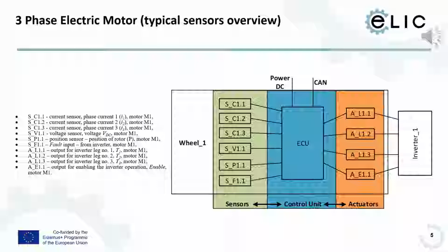So we have some mathematics and some diagnostics where we can see if the e-motor is perfectly controlled or not, because if the Kirchhoff law is not satisfied, the 3 phase currents are not 0 and not correctly coordinated, then the motor will not run perfectly. So it would not produce the torque expected.